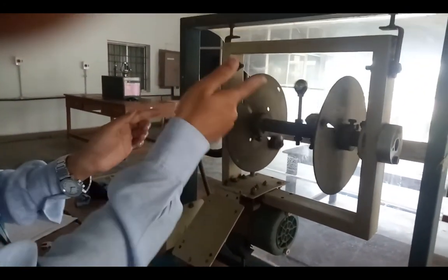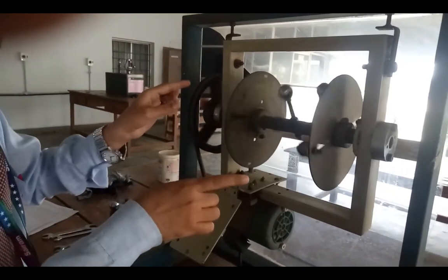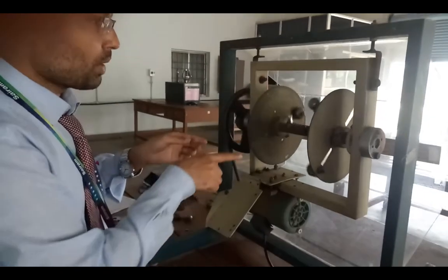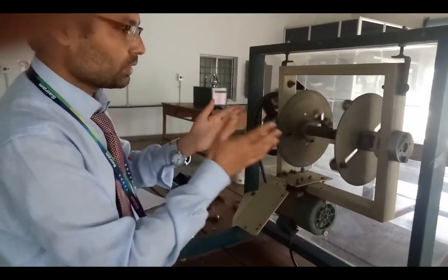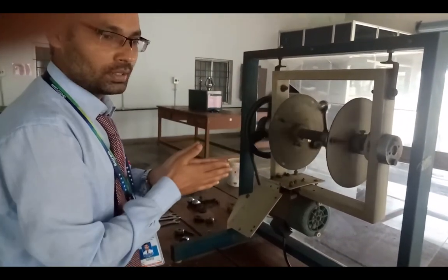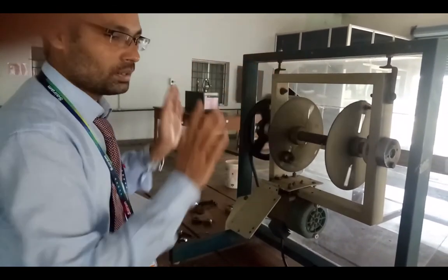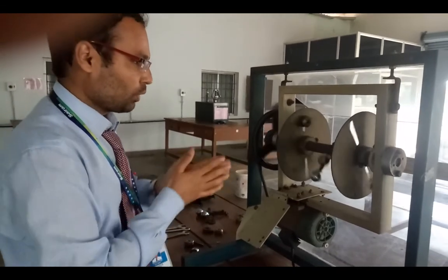Look at this. In the beginning, in the first session video, the whole component vibrates. But after fixing these two masses, it does not vibrate. This is the main purpose of this experiment. What we conclude is that we can control the vibration produced in the balancing of rotating masses. I hope you understand this.